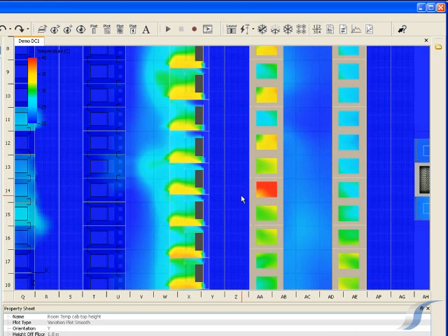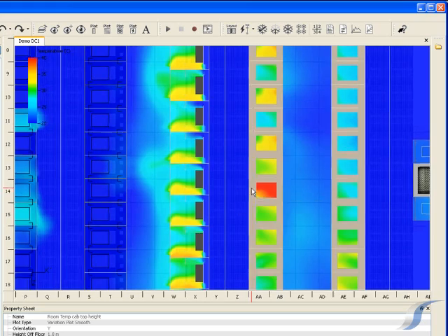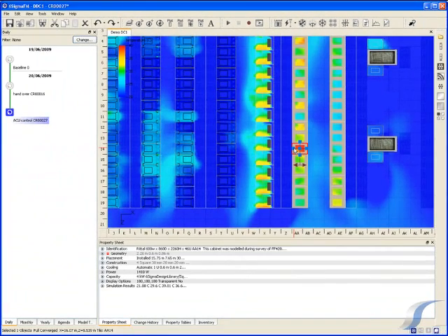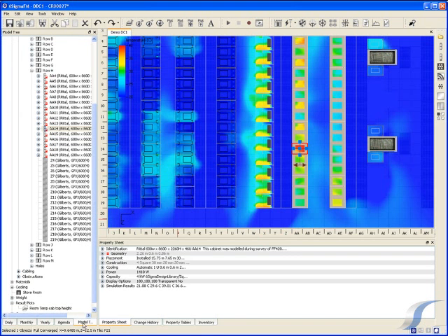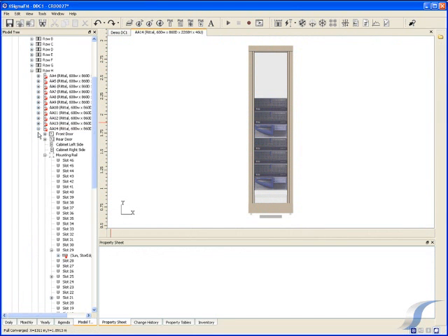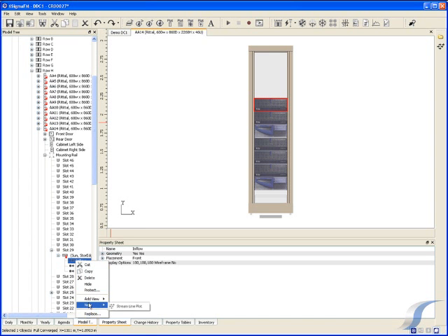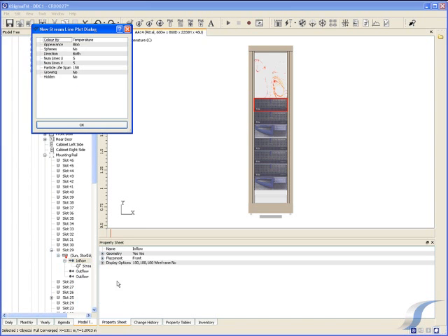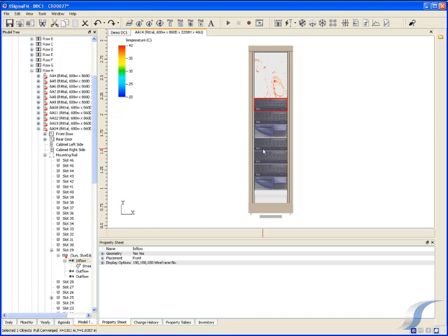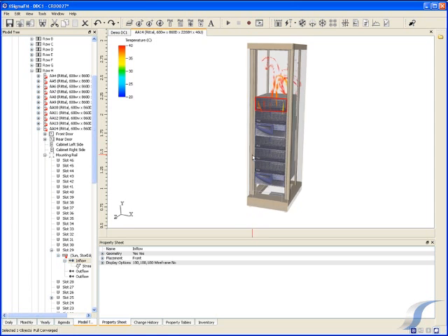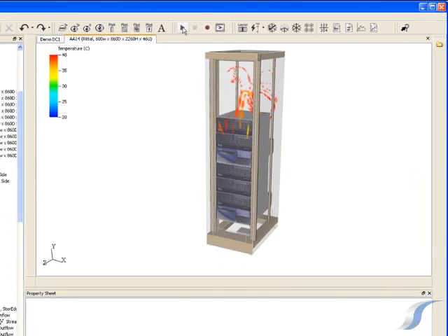We can see that the temperature in the cold aisle in front of the overheating cabinet is around 18 degrees C, which is acceptable. This means the overheat must be an internal cabinet problem and not a room-level problem. By adding streamlines to the inflow of the overheating equipment, we can see that air is recirculating within the cabinet. The hot equipment exhaust is being taken straight back into the inflow rather than exiting the cabinet and returning to an ACU.